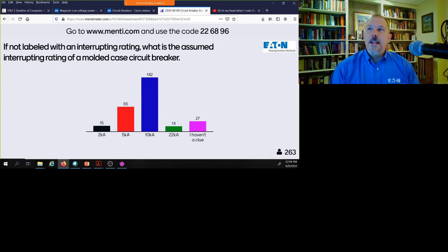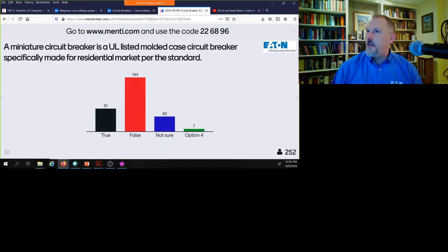So the first question was, if not labeled with an interrupting rating, what is the assumed interrupting rating of a molded case circuit breaker? 2,000, 5,000, 10,000, 22,000, or I haven't a clue. And the right answer on this one is 5,000 amps. We're going to go over the section of the NEC that covers that, but that's an important thing to remember. We're going to cover the details of that as we go through the slide deck. So that was a good one. 270 people responding. Thank you very much. Let's move to the next question.